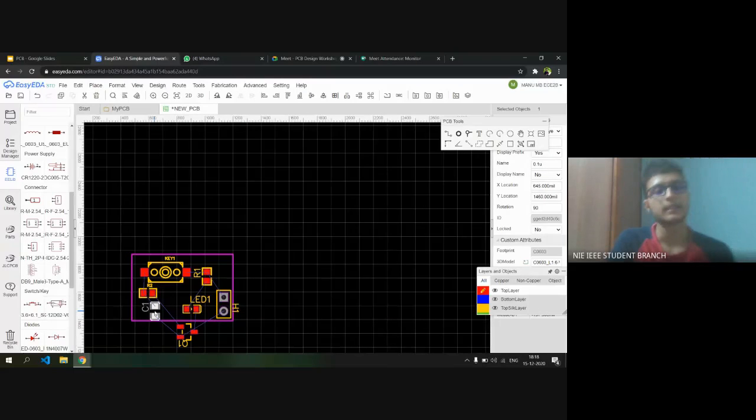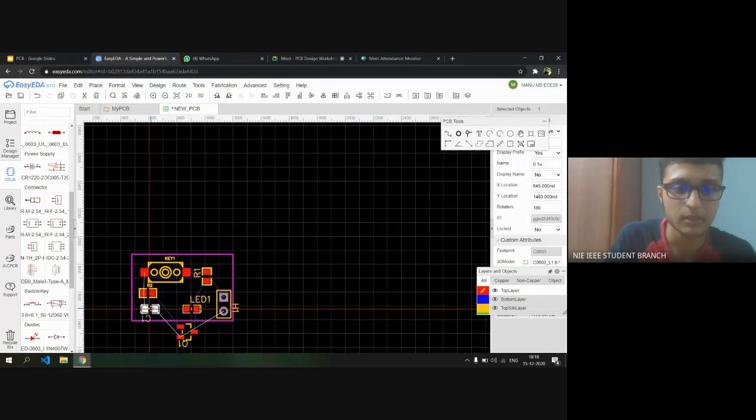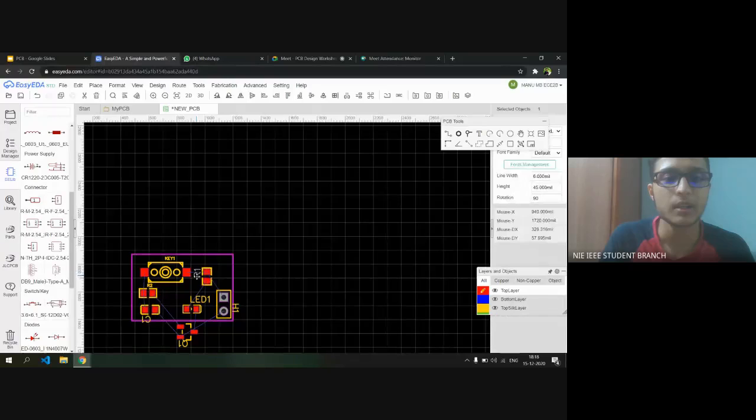Okay, placing it either horizontally or vertically is up to you, depending upon the routing techniques. Whichever is convenient, go with that. And the naming, just make sure it's all named properly. R2 is there, you have key 1, R2, and placing also matters. For a clean and neat design, if this is pointing upwards, let this also point upwards. Let everything be uniform. Just click this.